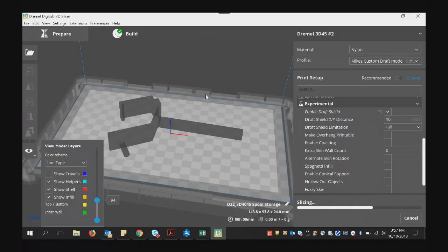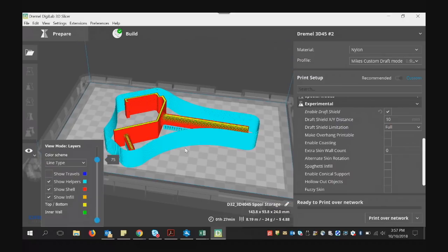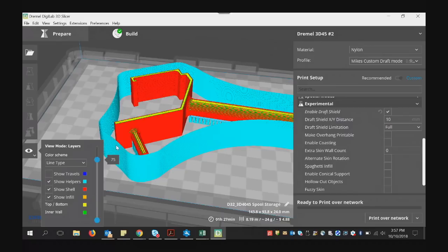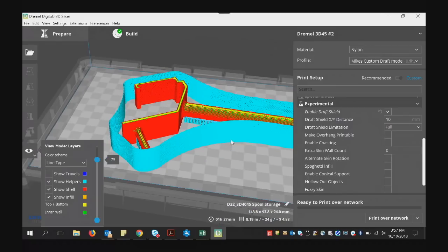So you'll see there'll be a single wall that actually goes around here. This blue area, basically, as you print, shields the object from any kind of air that can interfere with it, from warping or delaminating from the build plate.